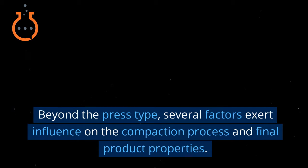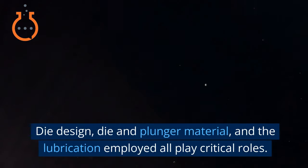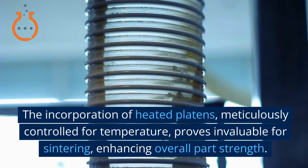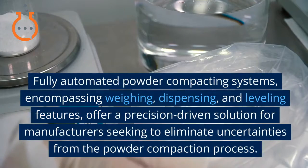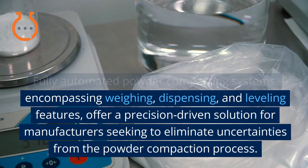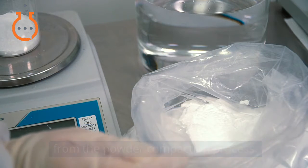Beyond the press type, several factors exert influence on the compaction process and final product properties. Die design, die and plunger material, and the lubrication employed all play critical roles. The incorporation of heated platens, meticulously controlled for temperature, proves invaluable for sintering, enhancing overall part strength. Fully automated powder compacting systems, encompassing weighing, dispensing, and leveling features, offer a precision-driven solution for manufacturers seeking to eliminate uncertainties from the powder compaction process.